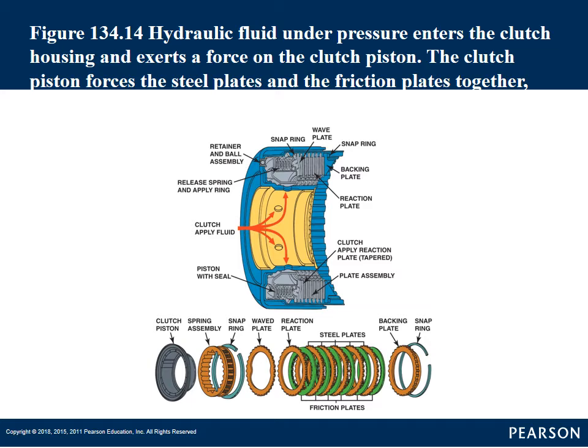But as we're seeing in newer transmissions, the piston has the seals molded onto it. So when you rebuild transmissions, you have to make sure you get those pistons also. A lot of your older stuff, you just took the piston out, replaced the new seals, and put the piston back in. On a lot of stuff now, you have to replace the whole piston because the seals are molded into them.